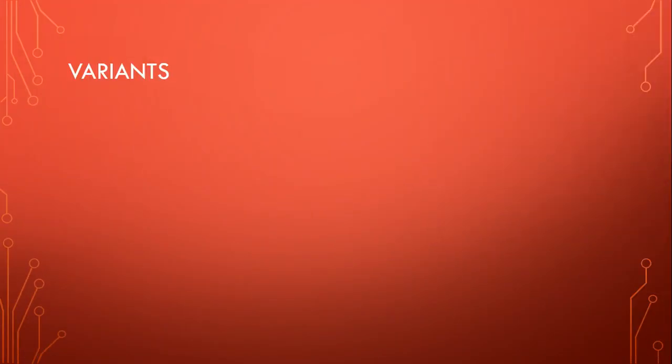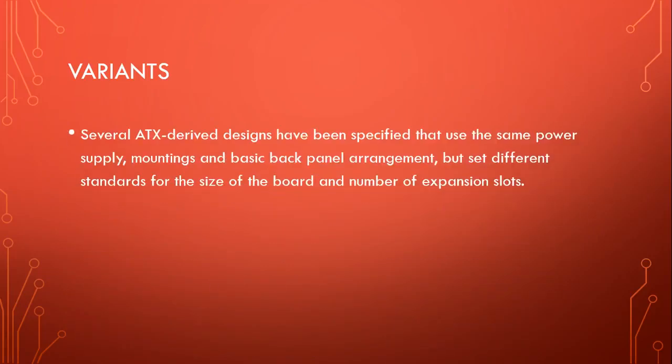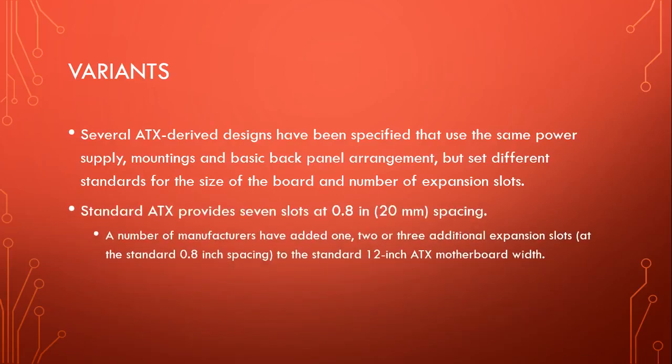All right, let's talk a little bit about some variants. Now, several ATX-derived designs have been specified that use the same power supply, mountings, and basic back panel arrangement, but set different standards for the size of the board and the number of expansion slots. Standard ATX provides 7 slots at 0.8-inch spacing. A number of manufacturers have added 1, 2, or 3 additional expansion slots at the standard spacing to the standard 12-inch motherboard width.